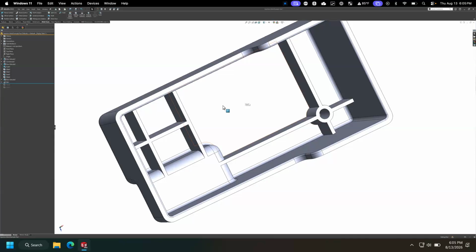Right. I think an example of that is we were doing some tooling for Dexcom actually, and we have some of the people here. There are some critical surfaces, for optics and other reasons, where it was like, hey, you can't put injection pins on these faces, even though from a molding standpoint, they absolutely would have wanted to. If you didn't tell them, they would have put ejector pin spaces. But you have to point to them and go, no go area, anywhere around that area.